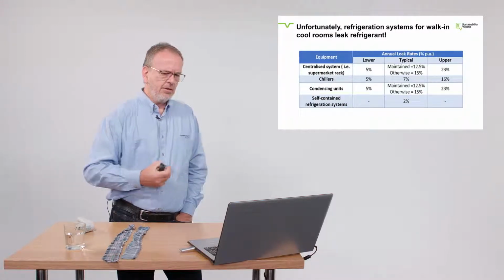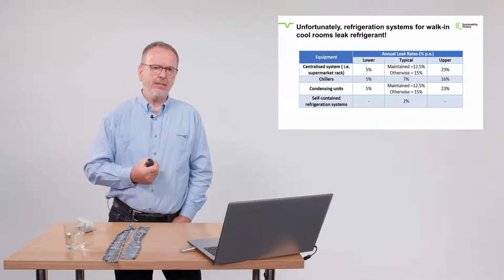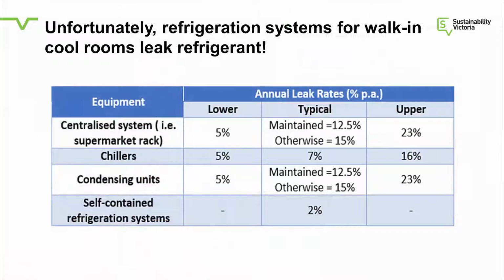And why do we have to look at these? It's because refrigeration systems leak. There's nothing we can do about that. Copper is unfortunately the widest used material, and copper has the material property that it hardens all by itself. So if you take a piece of copper when it's brand new, it's nice and soft, and you put it up on the shelf, and you can take it off 10 years later, it's a lot harder. All by itself, it just hardens. It's a crystallizing process. And if you subject that to temperature change and vibration, that process is accelerated.